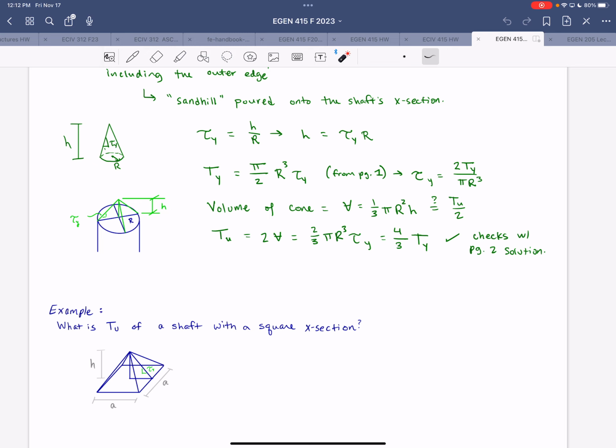And then for these two walls, you would cut here and look that way or the other way, and apply the same method. For the longitudinal stresses, that's just going to be whatever stresses are acting on the end surfaces. Those will be opposed by the material in the cross section. So, does that help clarify?